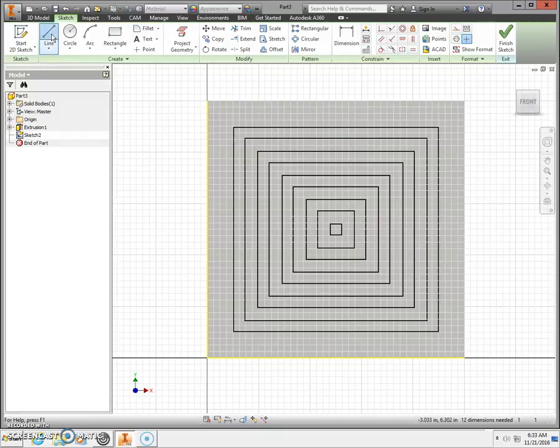Next I'm going to take and get my line tool. I'm going to start at the top. I'm going to click when I get a green point and come straight up. Make sure you have your object snap. That's that little gray box that follows your cursor up. Press the Escape key, line tool again. Come straight up. Click. And now we're going to use our trim tool.